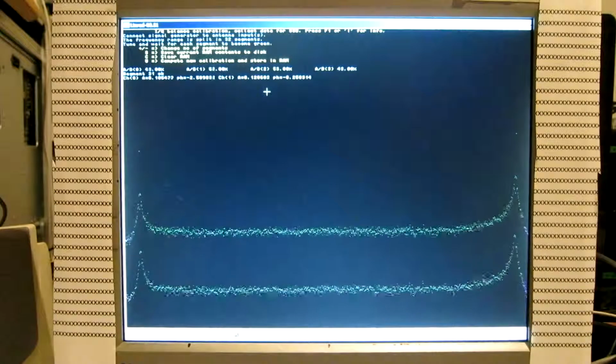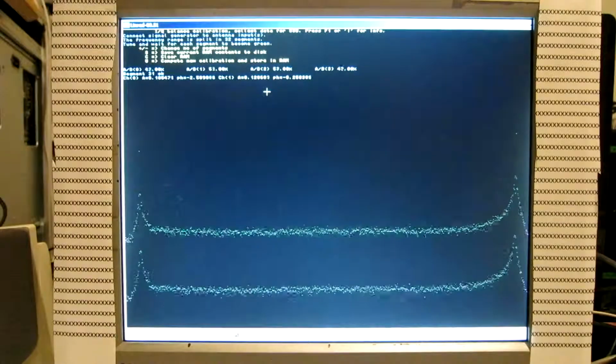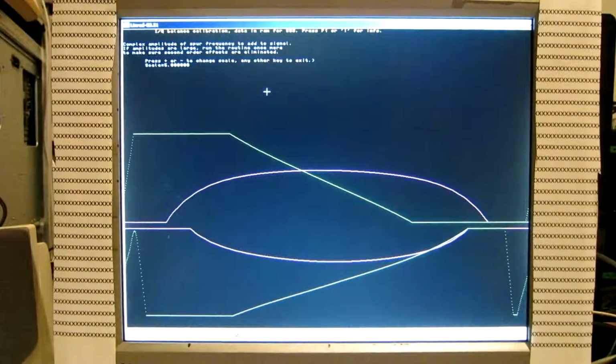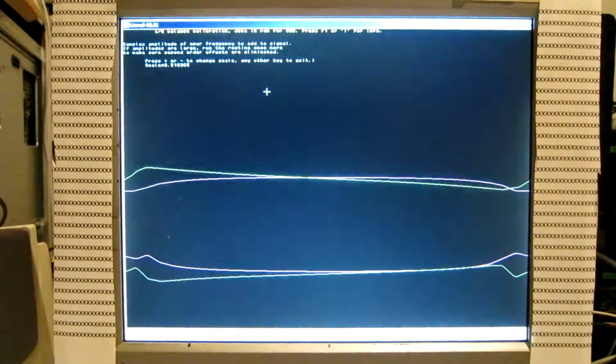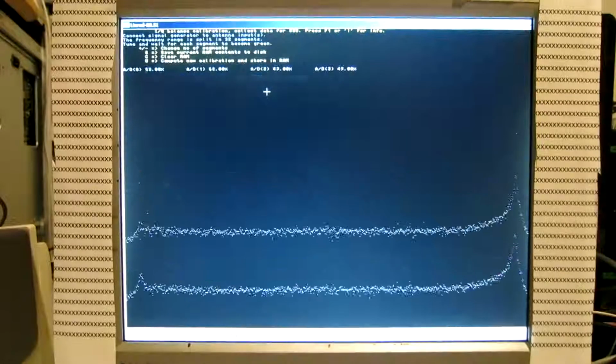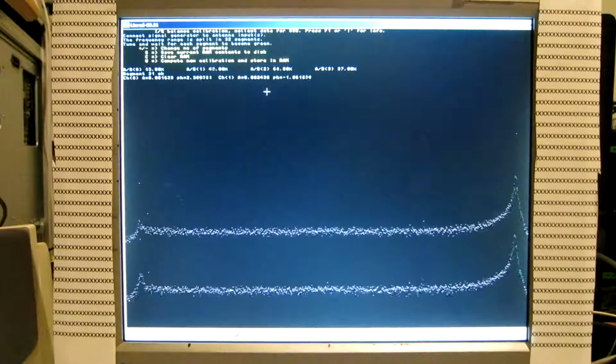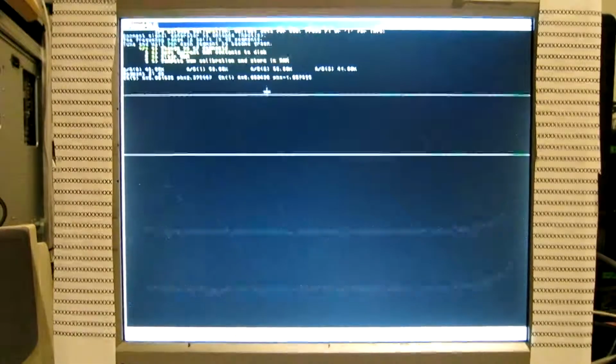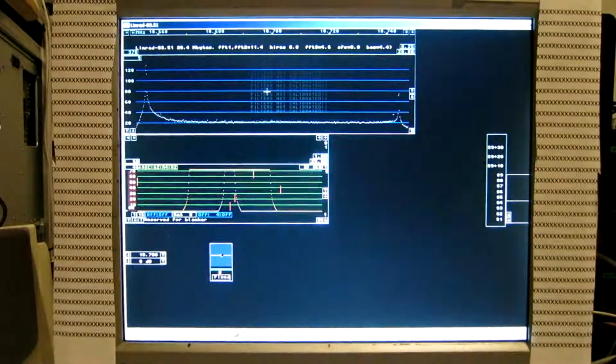So the next step is you compute the new calibration function. U. And to look at it, I press minus. And you can see, given the segment size 32 over the screen, that from here to here is about one segment. So 32 segments is not really enough for this hardware. But to show what result we got, I will accept it, press enter, and then just S to save, and X to come here and back to the processing screen.